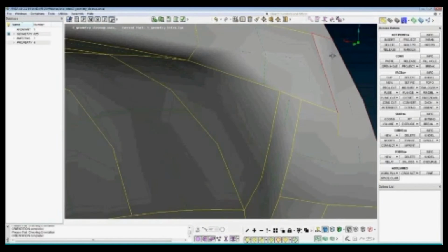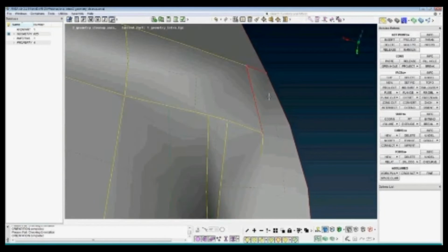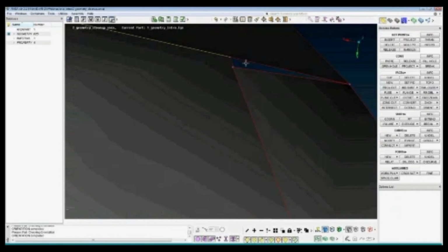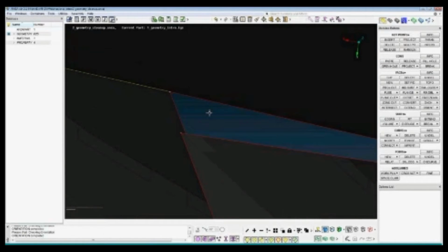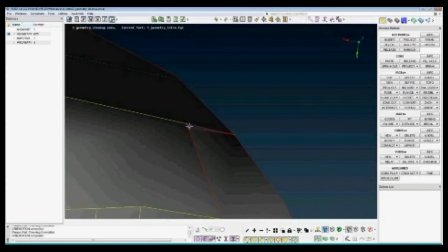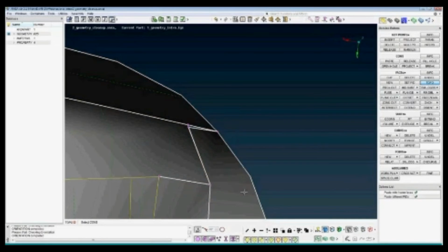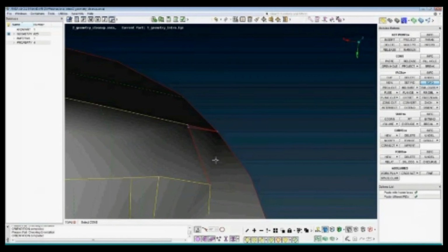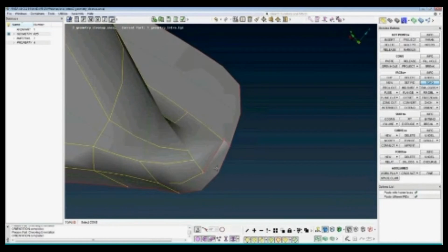We move to this area. We have red boundaries. This is not connected. And it's because the crack is larger than the tolerance. I can see my tolerances to the down left. They are smaller than a crack, so this area will not be connected automatically with the topo function. We need to paste this manually or create a new face.